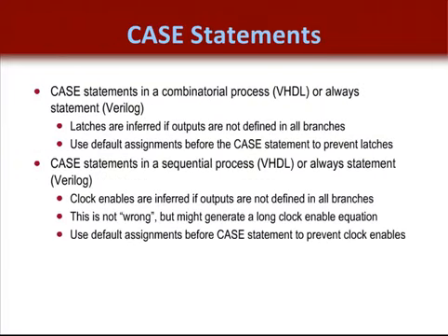Case statements are almost always the way to go when muxing logic. However, be sure to define all outputs in all branches. Otherwise, this will produce a latch and a warning message. To do this, we recommend using a default statement before the case statement. Case statements used in a register process or always statement can produce a long clock-enabled equation. So likewise, we recommend using a default statement before a registered case statement.